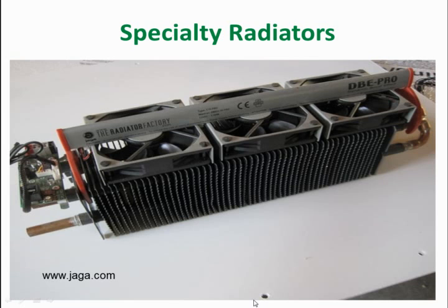But what they've done is they really boost the output of this element by forcing convection through it. Instead of just having natural convection where the cooler air comes in from the bottom, goes through the fins and gets heated up and comes out the top. Now by putting these little fans on there, they can boost the output. In fact, they're claiming about a 250% increase in performance from this emitter with the same temperature water by just forcing the convection through that.